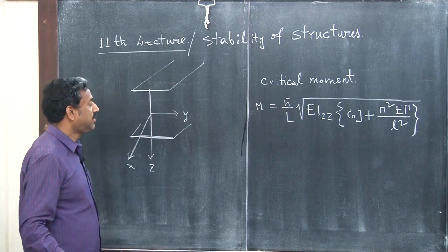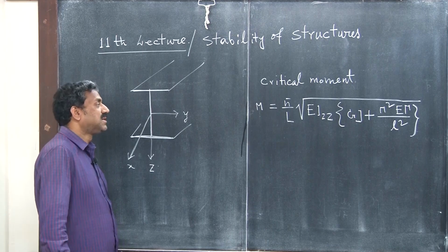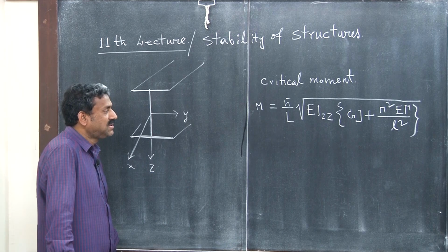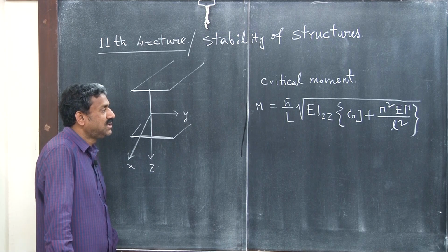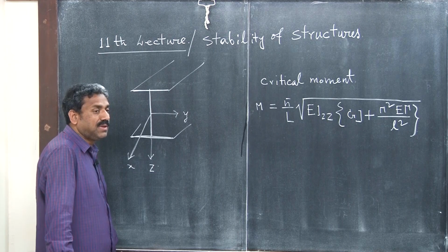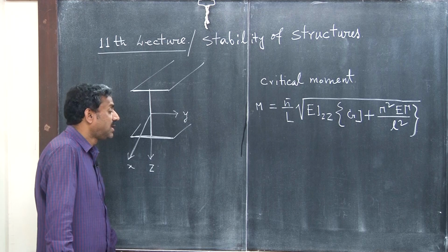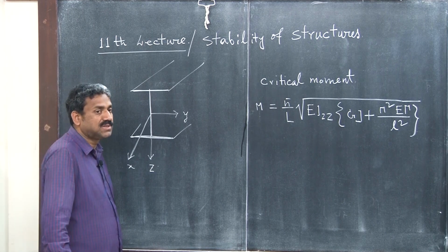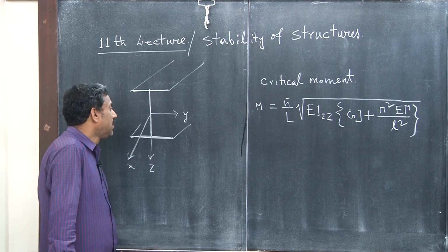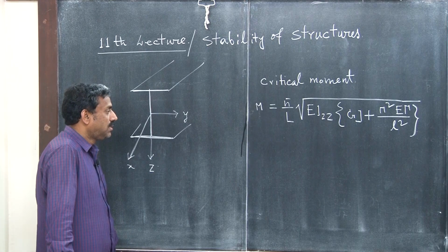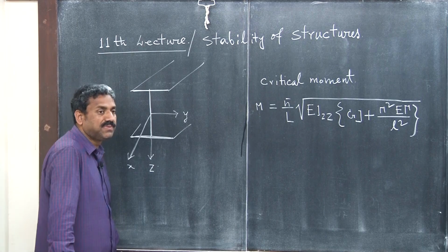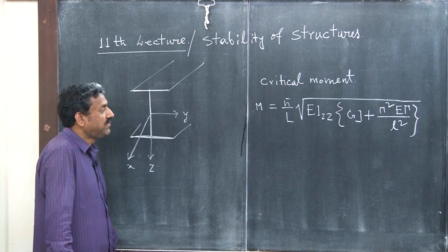We have assumed the I-section beam to be subjected to pure bending moment M. That expression is similar to the expression that you see in various standards for design, when you design a laterally unrestrained beam, especially the top flange, which is under compression. Of course, if there is a gradient in the bending moment diagram, there will be some modification to that.